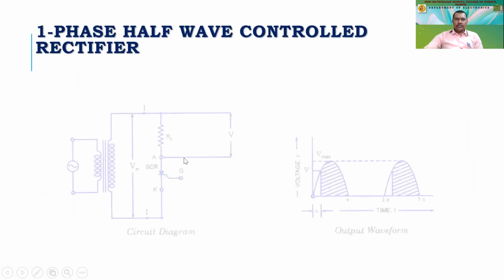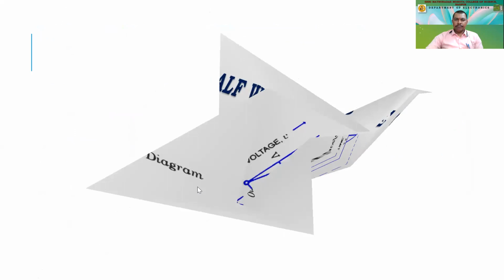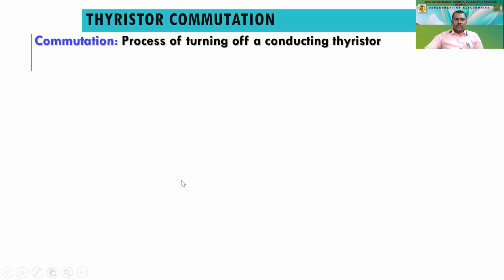So phase control, these are the applications of the thyristor. Here we have connected to a high voltage transformer. Here we are using an SCR over here, which is gated. So if you apply a sinusoidal wave over here and a high voltage is taken across the secondary of this transformer, then this type of output waveform will be appearing out of this because of the SCR characteristics. So this voltage is there. This is the application of that. We are less concerned with it.